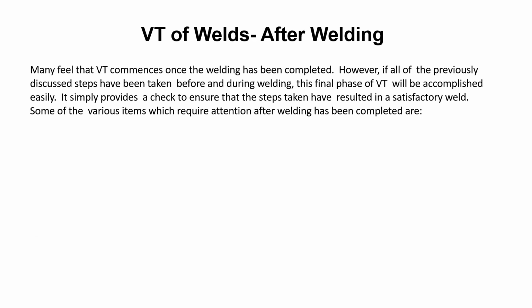So a lot of people think that VT commences once the welding has been completed. No. Visual testing of welds starts way before we even strike an arc. And it takes place before, during, and after welding, where we give it the final blessing, where we look at the surface, the final weld surface. But this makes sure that we've ensured all the steps have been taken to ensure that we've got a satisfactory weld.